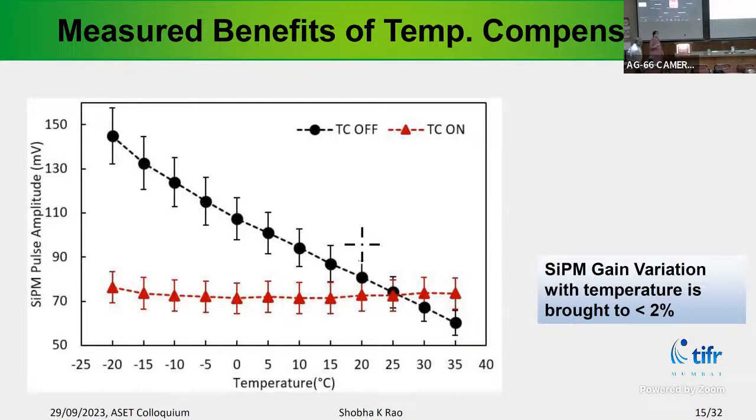Now, what is the question? No, my question is: why can't you operate at 25 degrees? You can have a jacket which can control the temperature, because unless all your components are temperature compensated, especially the resistor going to the bias, and if the output is very sensitive to the bias, in that case the resistor change itself will affect it.